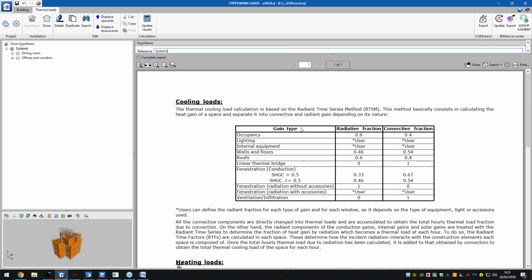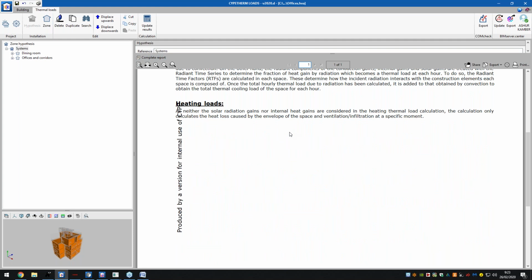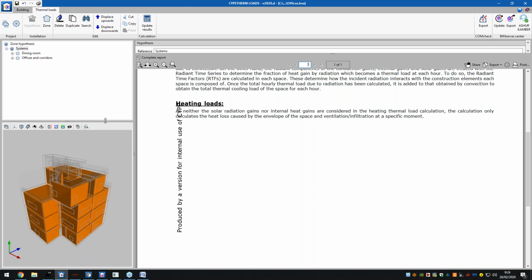Now, what we can do now. So of course, once we've configured our energy, our cooling loads model, by clicking this update button and updating the project, those particular specifications and reports get associated with our project. So when we move on to other programs within the workflow, our important data, so our peak heating and peak cooling loads, get transferred over as well. So we're able to, I'm going to show in just a minute, intelligently and accurately attribute certain air conditioning models to certain spaces, because we know those values to a high degree.